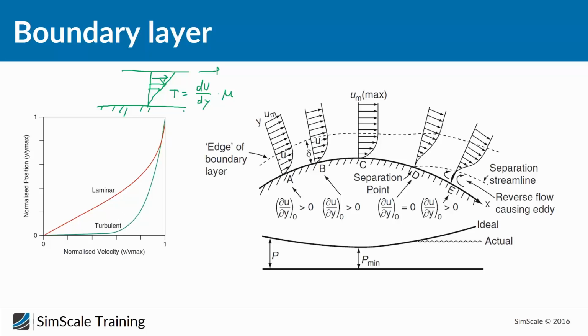And in the end, if you now take a look at the image on the right, when does the separation occur? The separation occurs when the adverse pressure gradient caused by the curved surface of the rear side of the ball, which you can see here, pushes the flow back and slows it down. You can see it here. So this is our velocity profile. Let me use my laser pointer. So this is our velocity profile. Flow is coming from here. And here you can see it, and this velocity profile is changing with time.